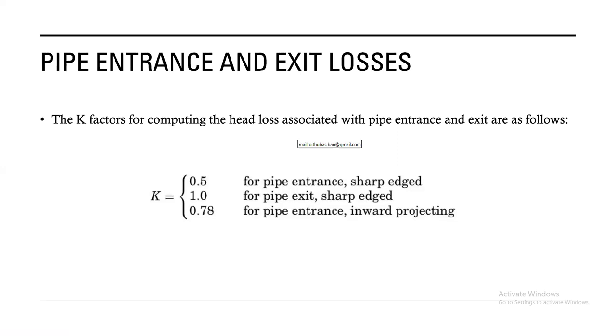And all these, why do you calculate the frictional losses? You want to know your system pressure loss or your system resistance. We call it system resistance to flow. Then you can use that system resistance to flow to size the pump which is needed for that particular system. And most of the time I talk to people, they don't understand what their system resistance is.